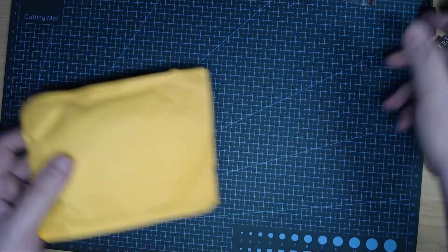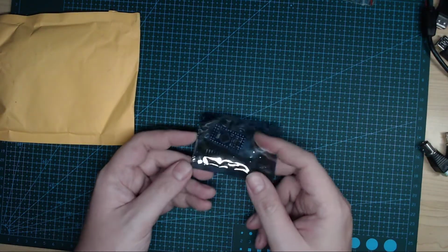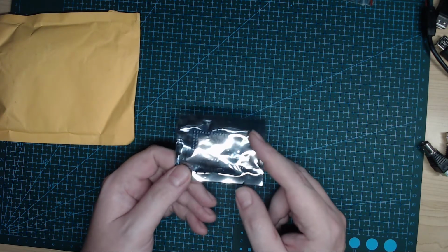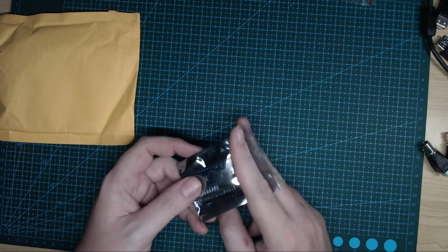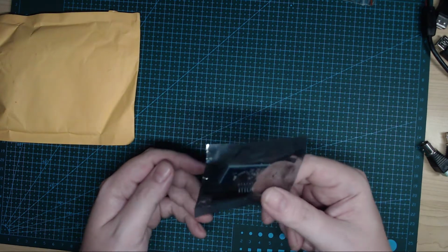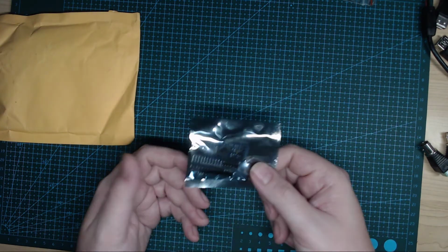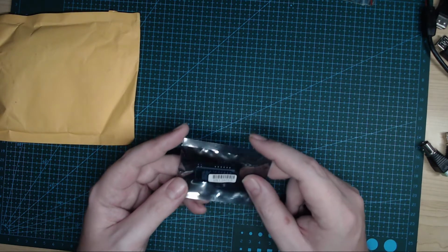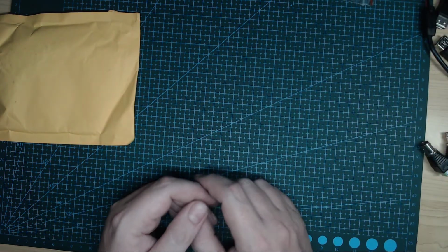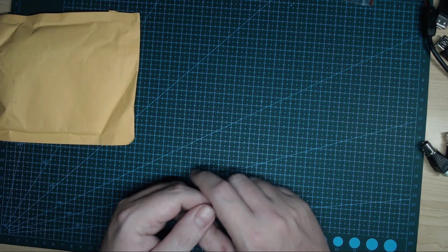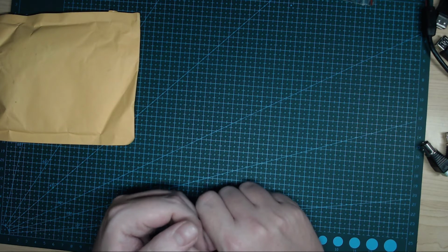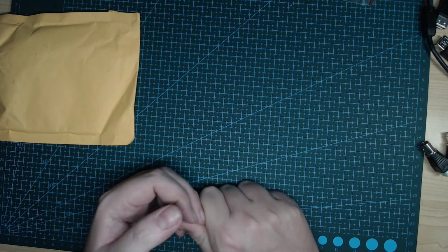I do equate these pretty much to the STM8 modules, which you can still get for under $1, whereas this is sort of $2 or $3. And the STM8 has very similar capabilities. Similar ADC speed and resolution, similar processor speed, similar flash memory, similar RAM, just, yeah, everything. So yeah, the STM8 modules are really good to play around with. The only downside with them is the compiler for them. People use SDCC rather than GCC, which in that case limits you to raw C code, not C++.